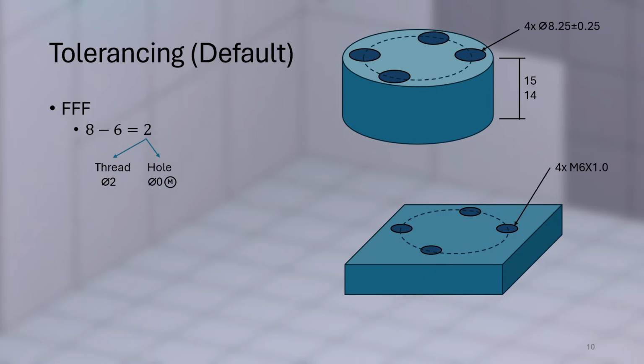And because I said that the lower part is really expensive and difficult to make, I'm going to give it the bulk of the positional tolerance. In this case, I'm going to give it all 2 millimeters of positional tolerance, and the clearance hole has a large size tolerance, so I'll say it's got 0 at MMC positional tolerance. And we'll say that's related to datum. Maybe there's some other datum structures in there, but for now we'll just look at the surfaces.